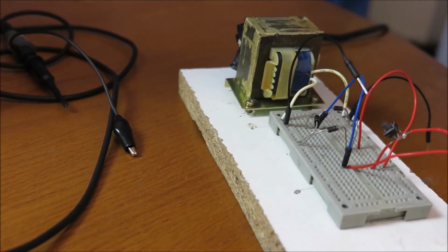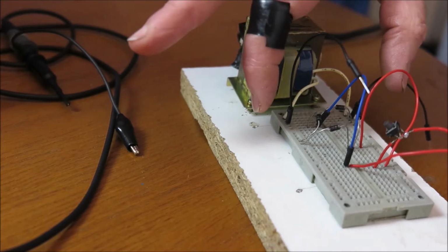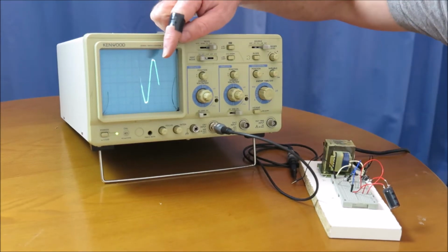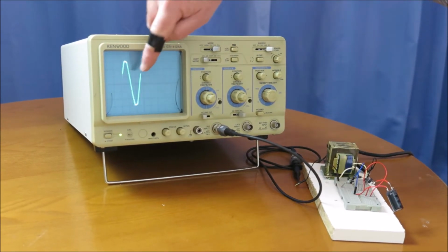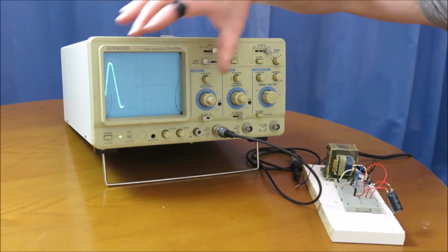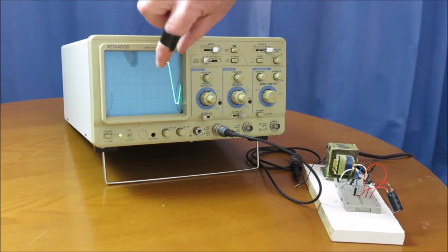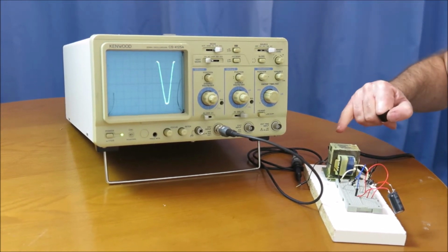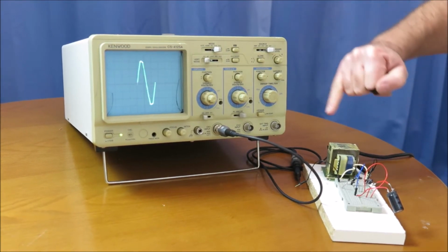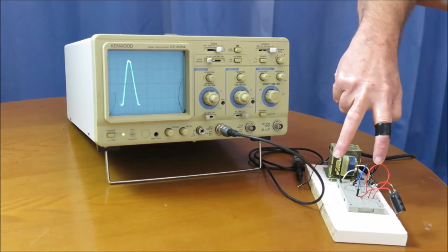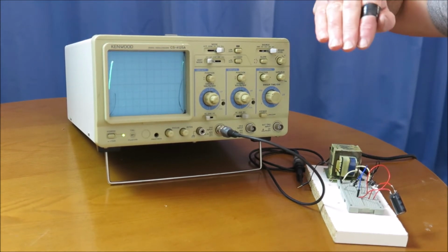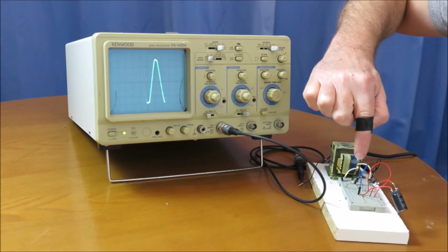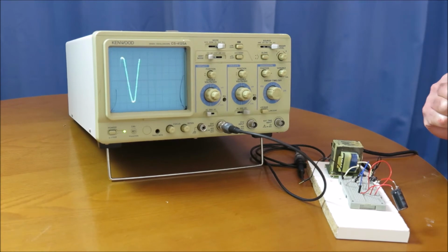So first of all, we're going to pick up the supply from here and have a look at it on the oscilloscope. As you can see now, we've got the output of the transformer, which is sinusoidal. That's an exact reflection of what's happening on the mains, only the voltage is severely decreased. So that voltage is about 17 volts there, whereas the mains is coming in at about 230. So we can see that we've got a lower voltage sinusoidal waveform there, and what we're looking for is that flat line. So we'll have a look now on the other side of the bridge rectifier to see what our signal looks like at that point.